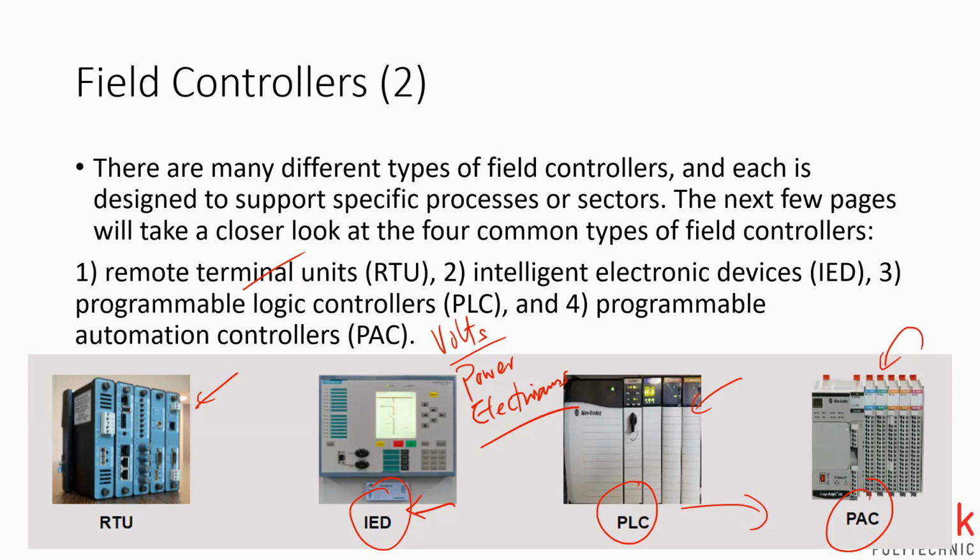Most of them are pretty reliable in today's context, and they have more and more features. It has blurred the differences. If you run TCP/IP, you don't really need an RTU anymore because it's remote, right? Your program just needs more RAM and more CPU, so there's no difference between the PLC and PAC. But we don't really like to call it PAC. Most people like to call them PLCs because that's what most people are using.